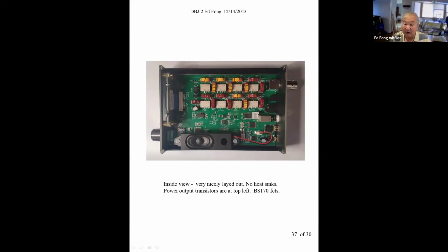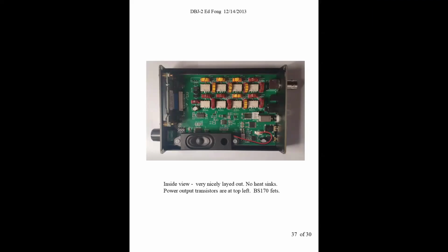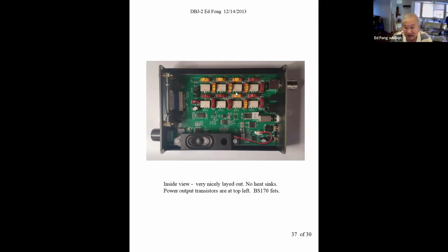You figure, how do you get audio out of a digital chip? You pulse width modulate the pulses, and then later when you integrate it, put a capacitor and a filter, put it through a speaker, the wider the width, the higher the volume, the narrower the width, the lower the volume, and it sounds pretty decent. You've got to hand it to these guys. I couldn't do it. I kind of know the theory, but to do all this, it's amazing.